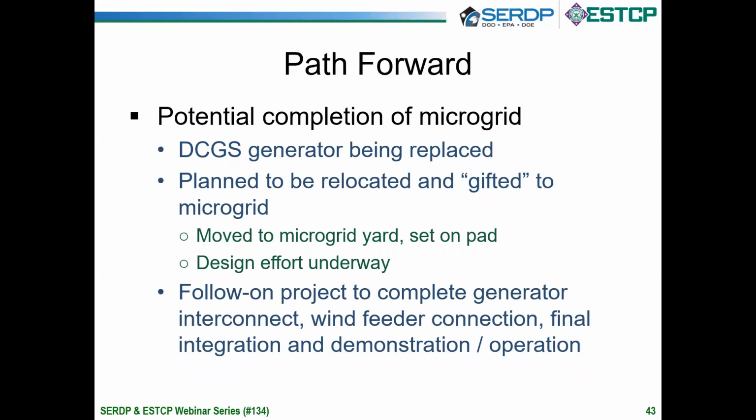Because the generator was taken away by virtue of the AFI compliance issue, we really weren't able to do much in the way of islanding. We couldn't island the system and run it on a consistent basis without the generator. The battery is a 1.6 megawatt, 1.2 megawatt-hour battery with a viable state of charge range of roughly 30 to 80%. So the effective energy in the system for a 1.2 megawatt peak load is relatively small, and we wouldn't be able to island the system for very long off the battery alone. The way the system was designed, at peak load, was to start the generator and base load it when the system went into an islanded mode. So once we lost the generator, we really couldn't do a lot there.